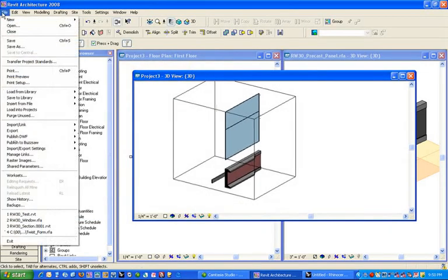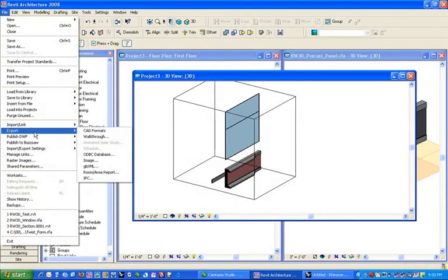You also have a couple other export possibilities. You have a walkthrough, which is an animation. You can kind of animate your camera. I've never really done that before in Revit. ODBC database, which is a database of your whole entire Revit file. You could open that up in Excel and start to quantify different things. A lot of estimators will take Revit files, open up an ODBC database, and start to extract quantities. So you can export the whole Revit file or views from a schedule.